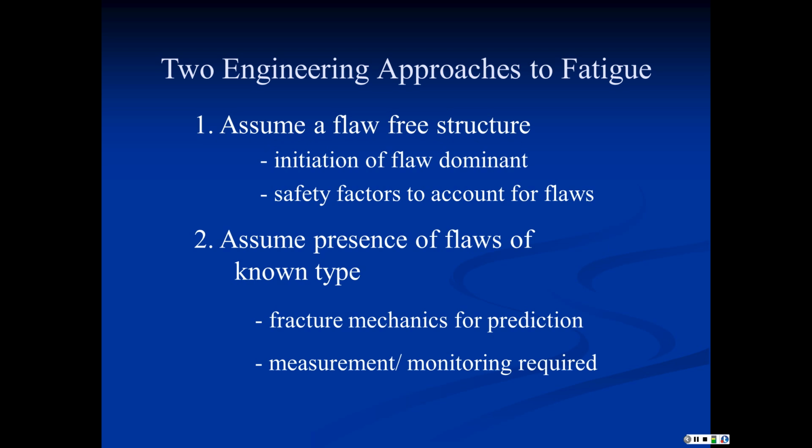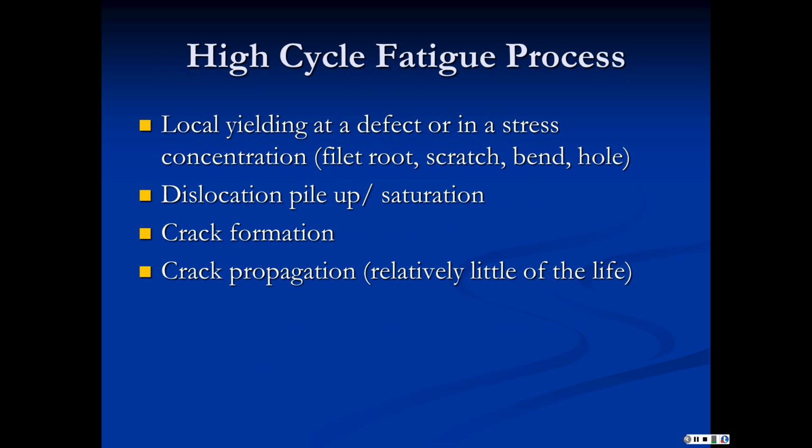And if the structure has a long lifetime and is at high risk of either loss of life or serious financial losses, then that structure may be measured or monitored periodically to track those flaws, see what's happening. And that's what we do with aircraft and pipelines and nuclear containment structures and other high-risk structures. We'll be inspecting them for the flaws.